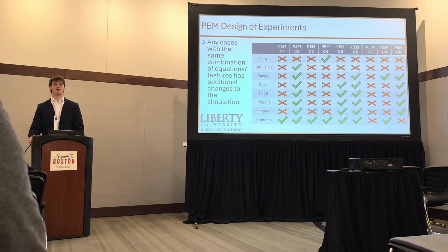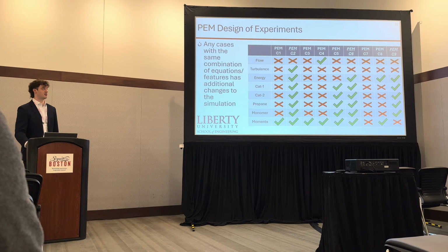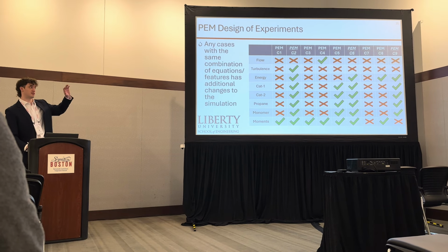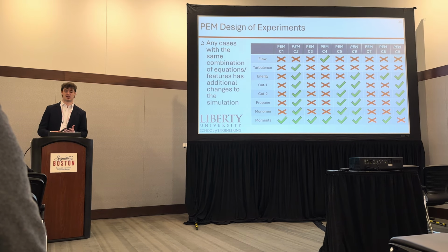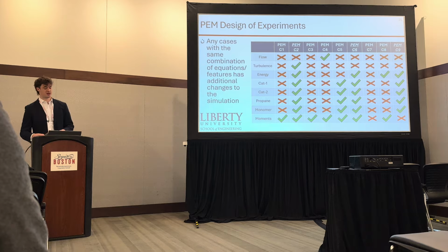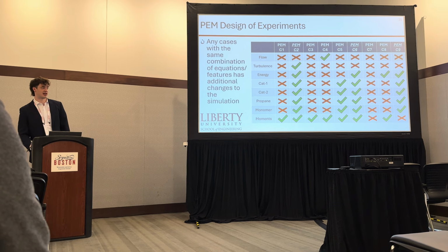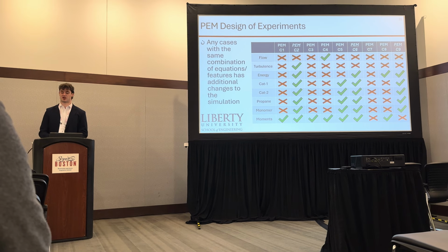Here is our PEM design of experiments. So we've run 9 cases currently, and we can disable the flow equations, turbulence, energy, the transport of all of our species, both catalysts, propane, and our monomer ethylene. And we can even disable the equations that calculate our moments because they're implemented as user-defined scalars in our solver.